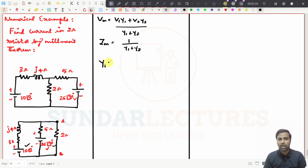So what is y1? Y1 should be equal to 1 by Z1. See, this is Z1 and this is Z2. Z1 will be 3 plus 4j. If you simplify this, you will get 0.2 at an angle of minus 53.13 degree.